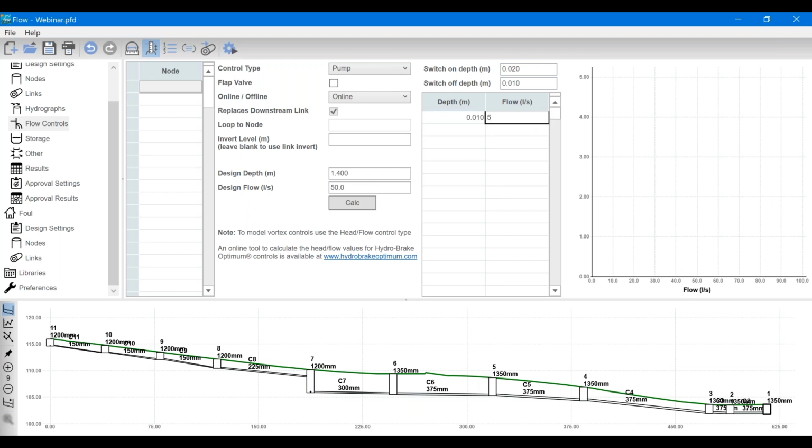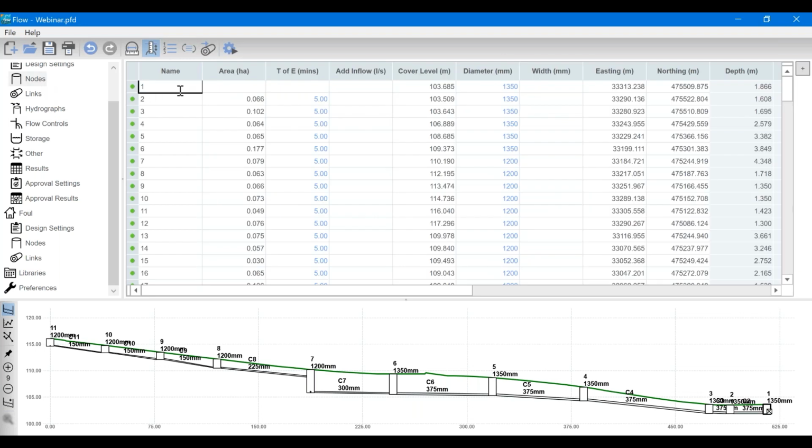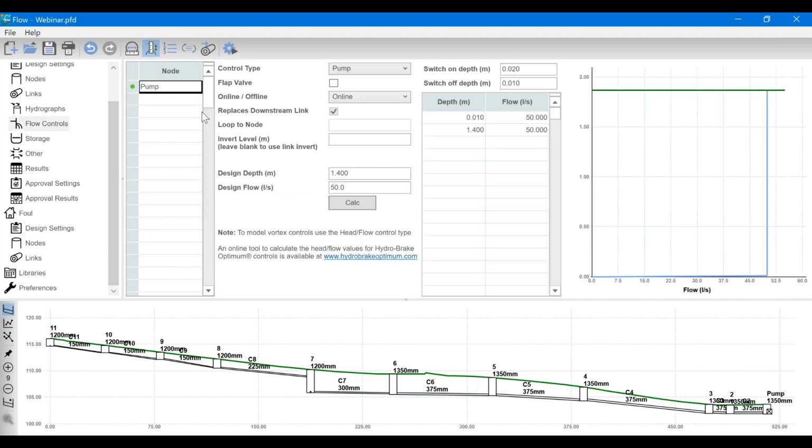So now if we edit the node name where we have the pump, because we have a cascade rename switch in preferences, you can rename cascade to all ancillaries.